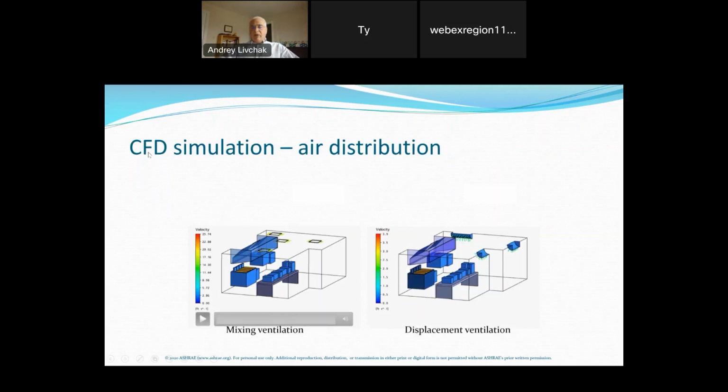Again, I'm going to show you a comparison of mixing versus displacement ventilation in a kitchen environment. Here we have a typical quick service restaurant kitchen. We have fryers and a broiler, a hood above them, an island with heat producing equipment, a mixing system with a four-way diffuser on the left picture, and displacement ventilation on the right side. You may be asking why we have a displacement diffuser at the ceiling level here, and the explanation is very simple.